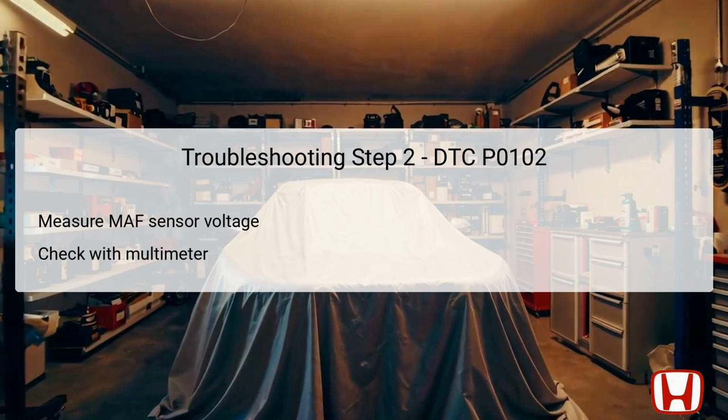If the voltage is falling below this threshold, it reinforces the likelihood of a malfunctioning MAF sensor or associated wiring issues. Make sure the connections are secure before taking measurements, as loose connections can lead to erroneous readings. Document the voltage readings as they are essential in guiding the next steps in diagnosing the issue accurately. This measurement is critical as it directly reflects the operation and health of the mass airflow sensor.